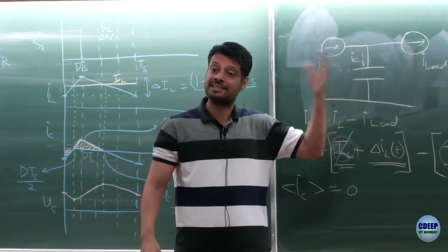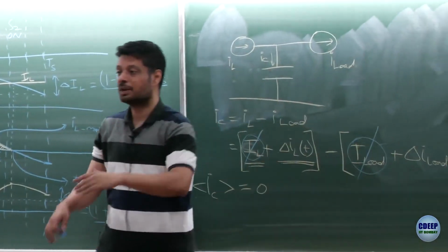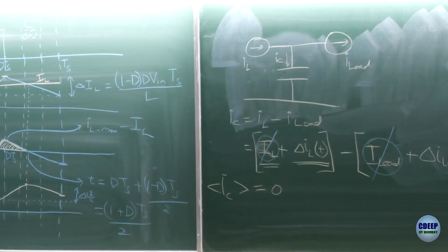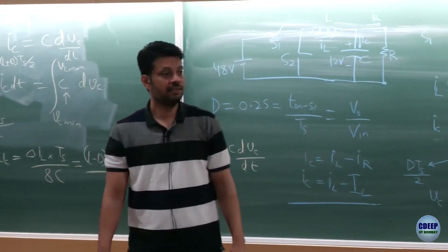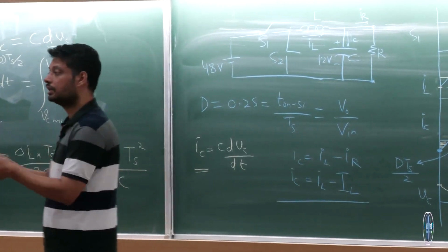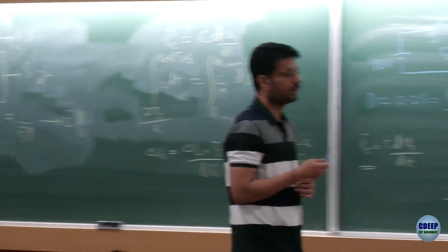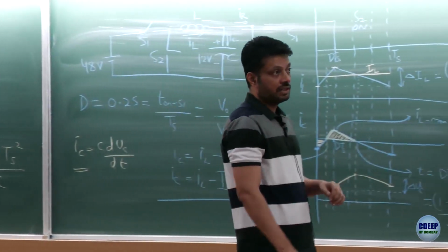And now you have to size the capacitor so that even with this kind of load, your ripple is 1%. Is that okay? Is that fine? So this extra horn would actually increase your burden on the output capacitor. Any question? Any doubt?